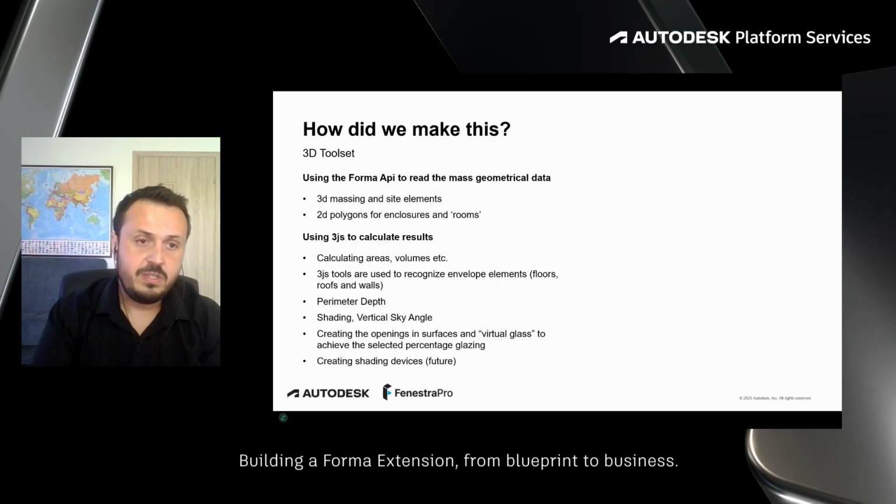And then we need to have a closer look at the floor plans. From here, we need to see, okay, what do we have there? What is the outline of the floor plan? What are the exterior walls? What would be the interior walls if, for example, the user defines the internal separation lines? Then we need to take all of these points and create the analytical spaces. That's the very first step we are doing.